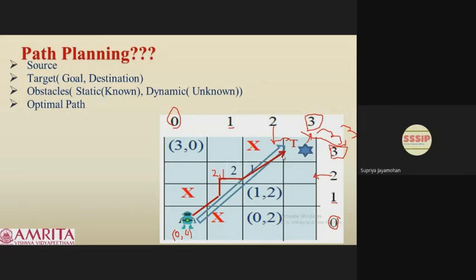We can also see one more case, which is the third case, and here you would see that it is starting from the starting point, it is avoiding the obstacles, and still it is reaching the target. What is of significance to us is a term which we call the optimal path, which means we would like the robot to reach the destination with minimum distance. This distance is generally calculated as the Euclidean distance, and we could see several other types of distances also employed in various algorithms.